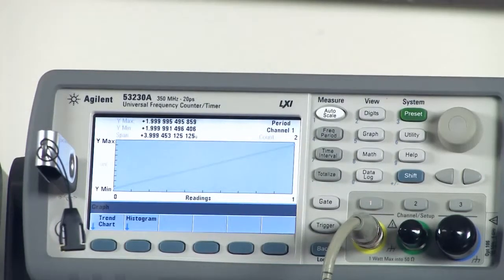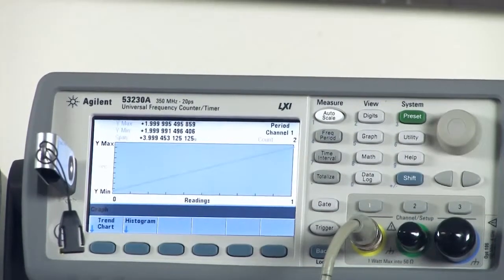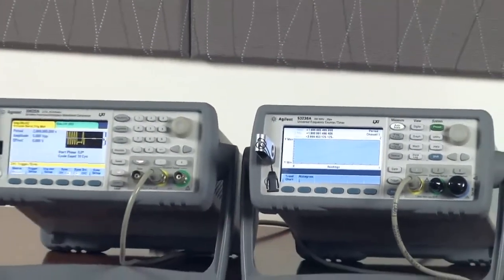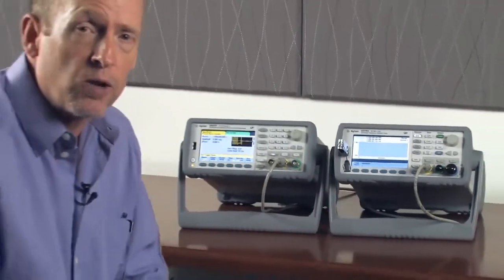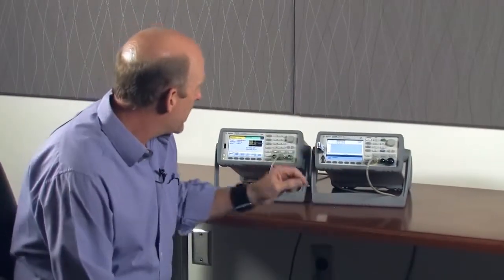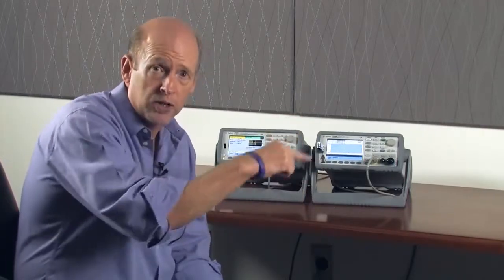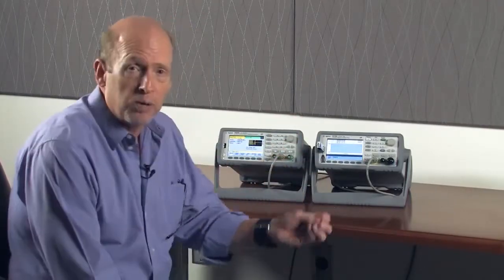And as we continue on, we wait for the next number of cycles to occur, and our reading count is 2. Now keep in mind that we have programmed the function generator to give us 10 cycles. We are in the auto mode of the counter. Auto mode, again, there is an open and close gate sequence for each reading. What is happening is for each gate sequence, there's an additional number of cycles that are required in order to produce the reading.